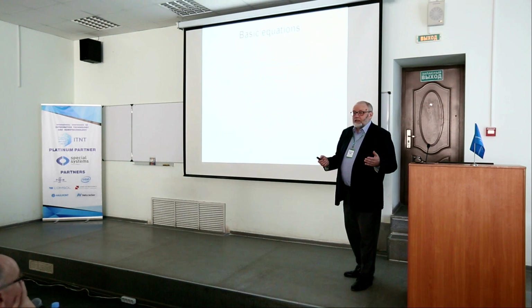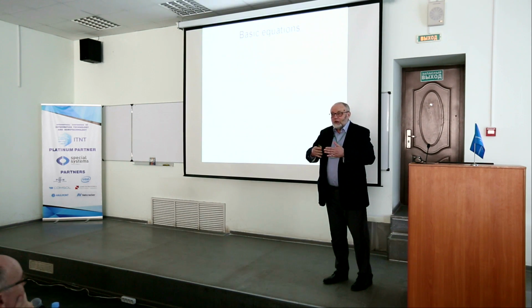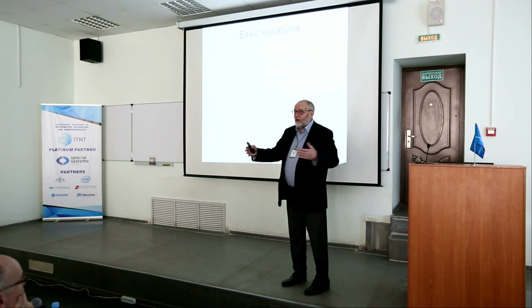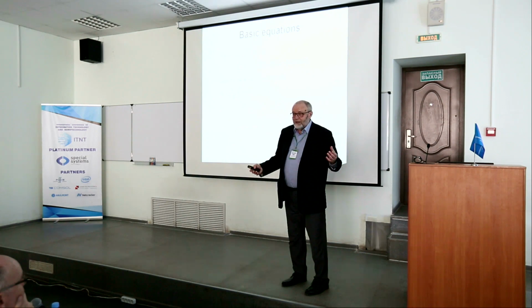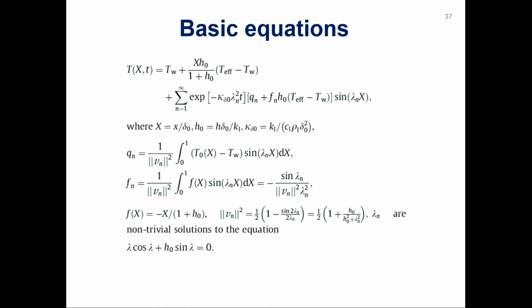Obviously, this solution was not used during the whole period of film heating and evaporation, but it was used during a small time step during which the heating and evaporation of film takes place. And if it is used at the small time step, then in fact this solution is incorporated into numerical code. So that means that the main objective of this solution is not to use it in isolation, but to use it as a part of the numerical code.